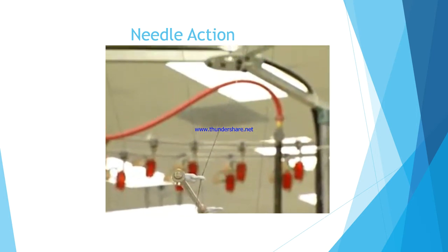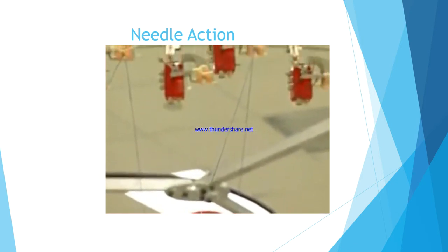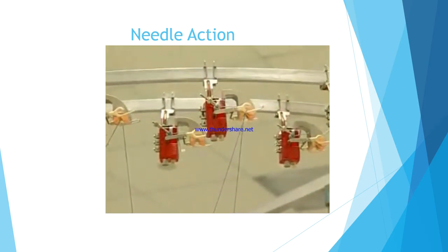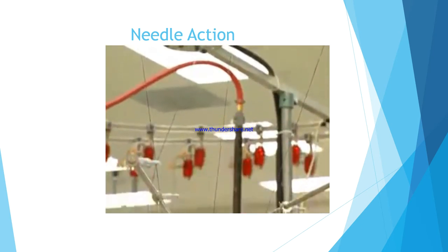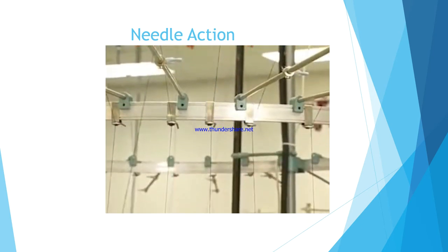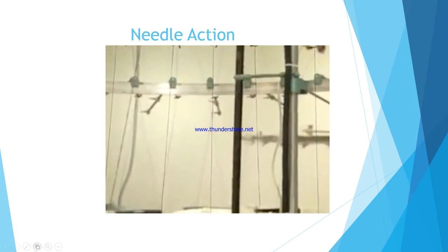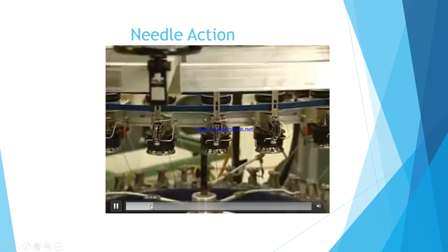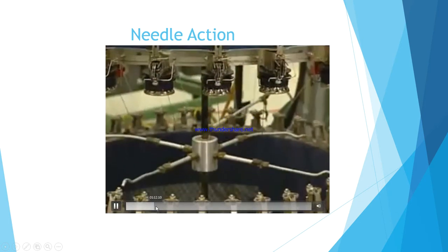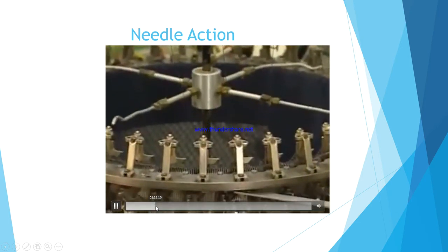Fed from above the knitting elements, yarns move from the yarn supply, or creel, through guides to stop-motion controls above the machine, then back down through tension controls and yarn feeding devices to the knitting elements. Quality products can be produced only when stop-motion and yarn feeding functions are properly set.